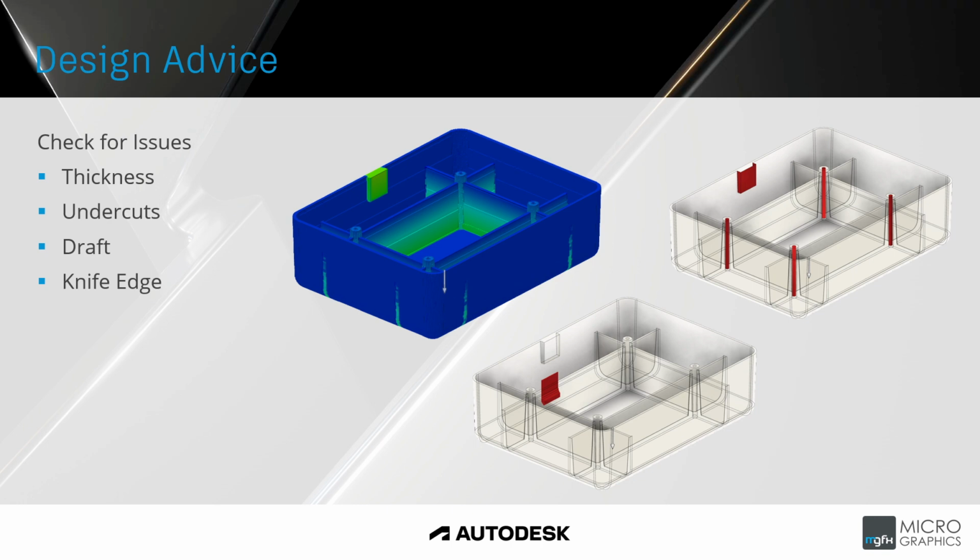Another thing to look for would be undercuts or overhangs. The bottom image shows an undercut where you may need to have a slide or an insert within the mold to help with the molding process. Then we'll look at the top right image where we have a draft analysis. Those faces that are highlighted in red do not meet the required draft angle set in the rule for the active plastic. In this case, they have a draft angle of 0.